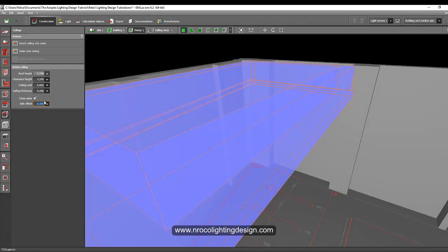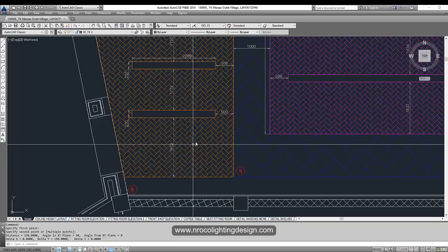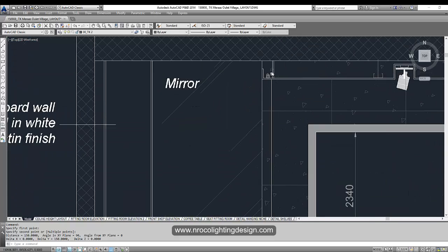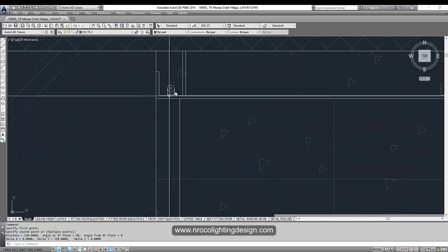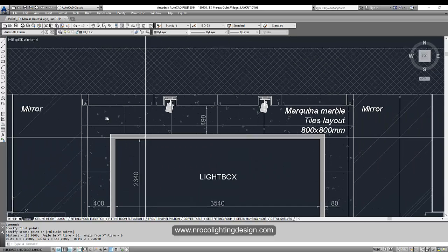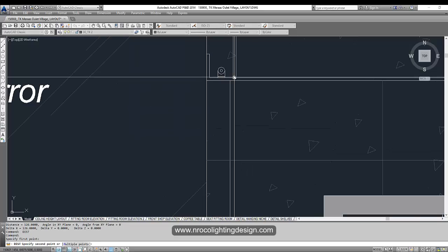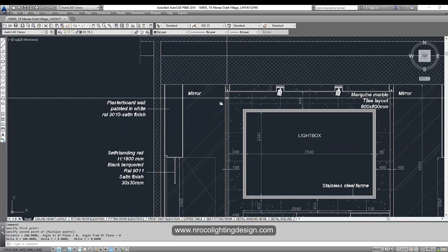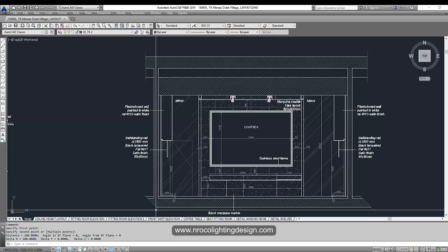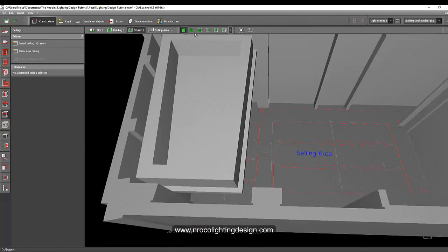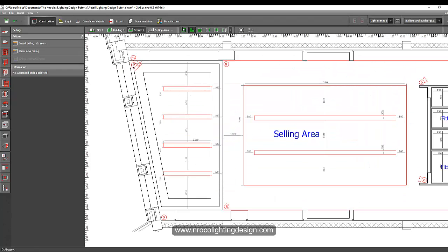Or can we make it 0.15 so it's much better? Or can we double check it in the section if there is a section? There you go. Here, it's here. So can we check it? DI. How about inside to inside? It's 100. Okay, so let's just make it 100. So we now have our first drop ceiling, and let's create now this groove.